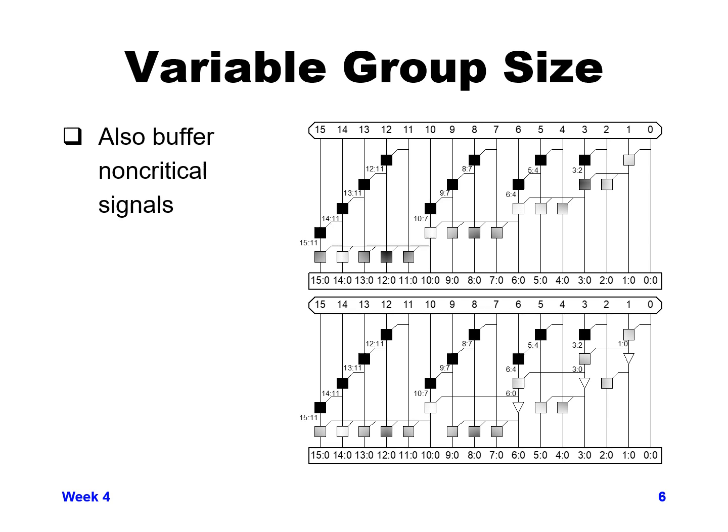And then what's shown in the bottom figure is something that doesn't reduce our number of delay stages, but it's something that can reduce our total delay. So note that the output from bit 3, if you look up in the diagram on the top, needs to go to 3 receivers, bits 4, 5, and 6. So it has a fan out of 3.